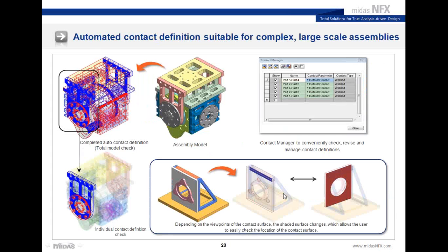The Midas NFX provides you a very convenient method to define your contacts in the model. So if you have very large assemblies and all of them need to be assigned a welded contact, you can just click on one button and automatically the contact will be assigned between those geometries. And